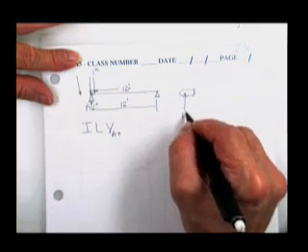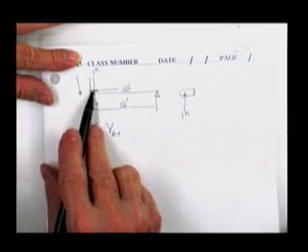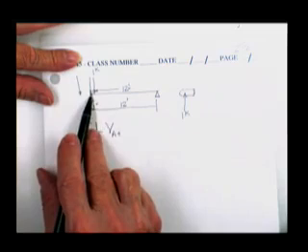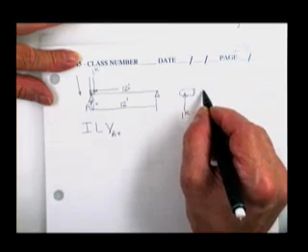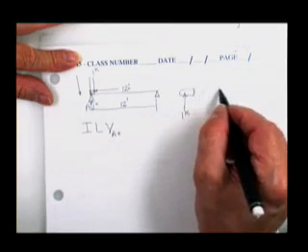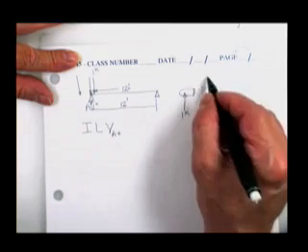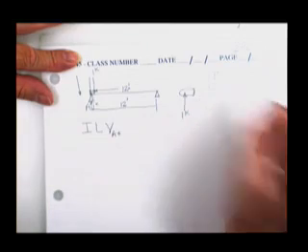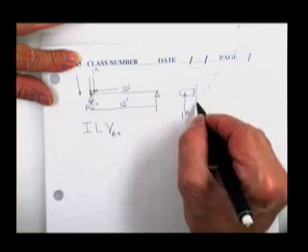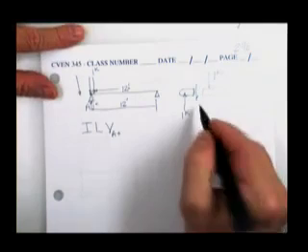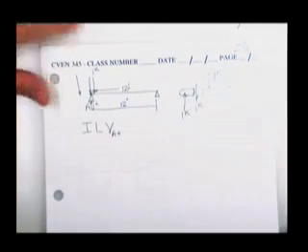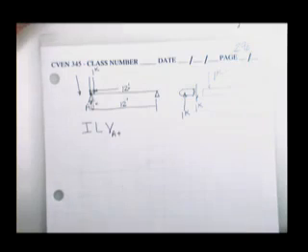You'll notice that my slice line, I moved the load on the beam a little to the right, so you can't see it. And there is a shear that you caused inside of the beam of 1 kip. The reason is that little piece of steel has to be in equilibrium.